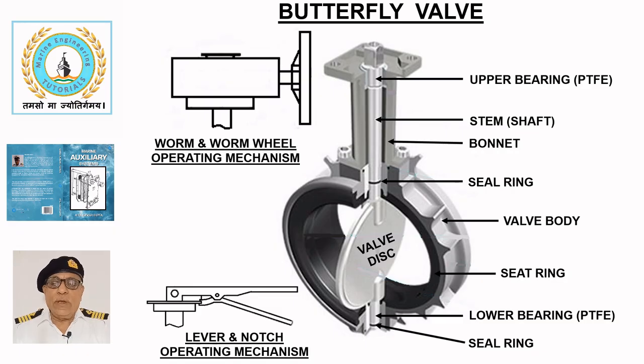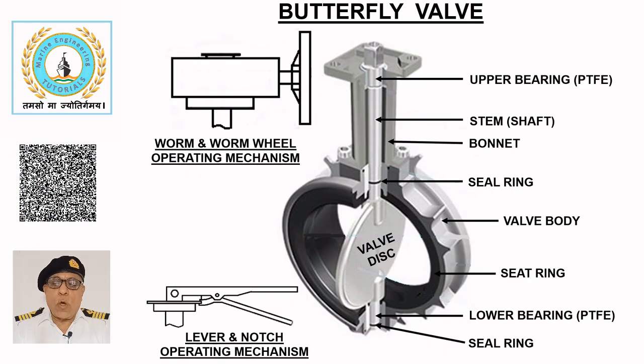The valve is quick acting, requiring only a quarter turn of the spindle to move it from fully open to fully closed positions. These valves are particularly useful for remote operation in ballast systems, bunker transfer, and cargo operations on oil and chemical tankers, when operated with a linear actuator using air or hydraulic fluid as a working medium.